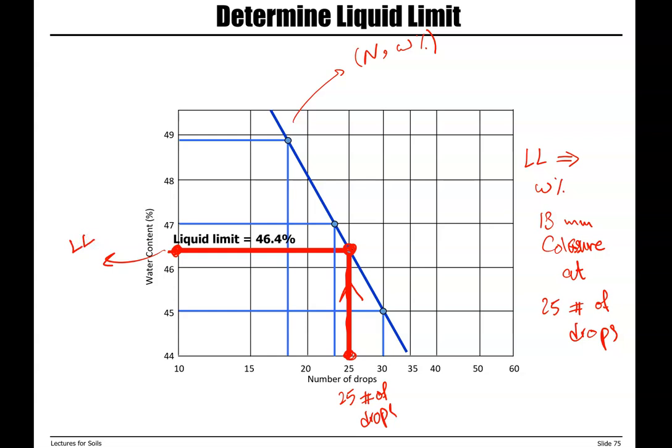The water content at which the cut that we make is visibly closed for half inch or 13 millimeters with exactly 25 drops. So LL is 46.4%.